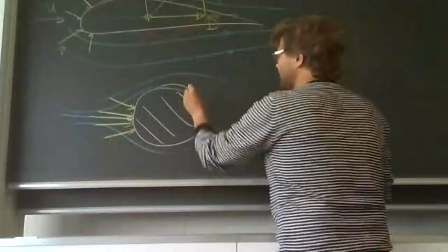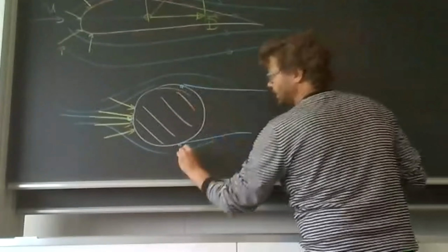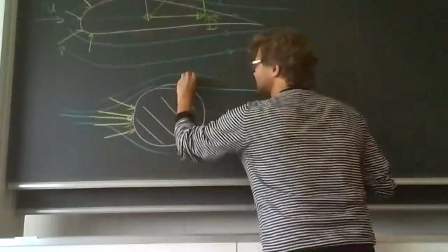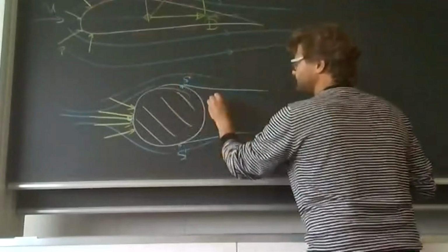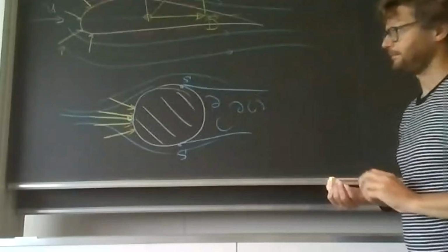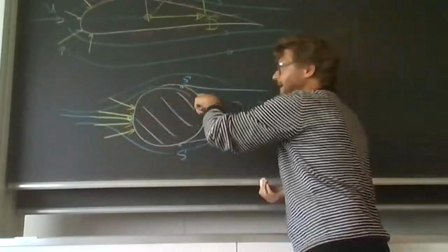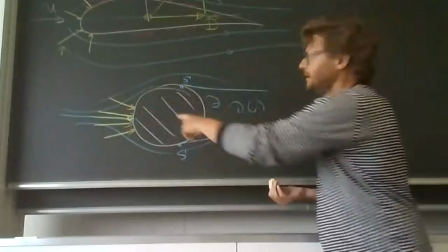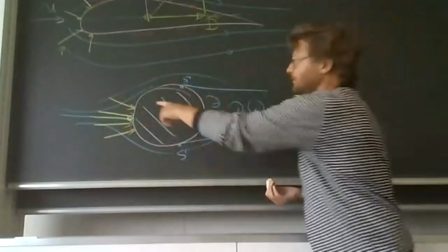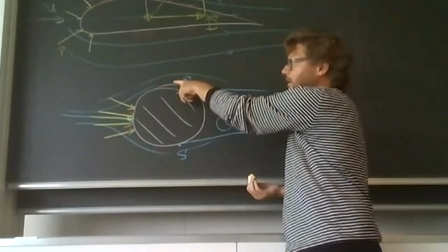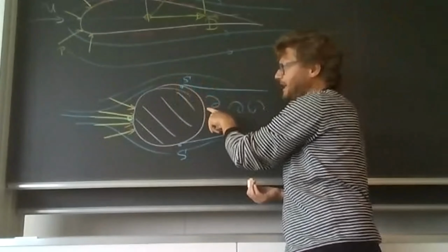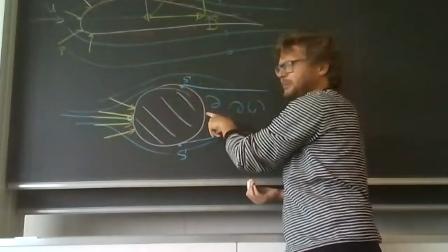What is happening now with the flow separation, here at the separation points, we get this turbulent wake. And locally, because the flow is accelerated, we have a pressure minimum, and in potential flow, the flow is decelerating again and coming to a halt here, so we have again a pressure maximum.